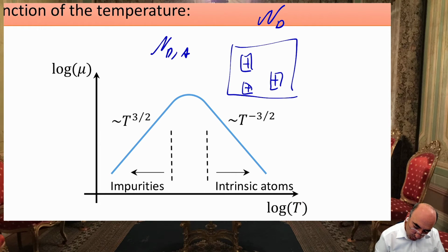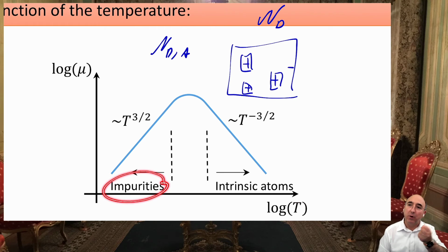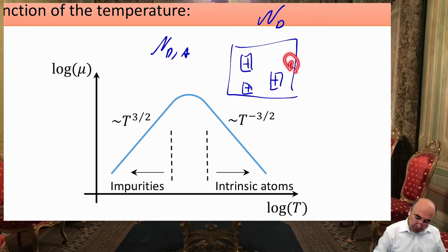Okay, let's talk about one electron. The trajectory of this electron is somehow this way and this way through the semiconductor because of the impurities' attraction, the Coulomb scattering, because of the Coulomb law. If you increase the temperature, the movement of the electron also increases. And the Coulomb scattering force, which tries to catch the electron, is getting less.